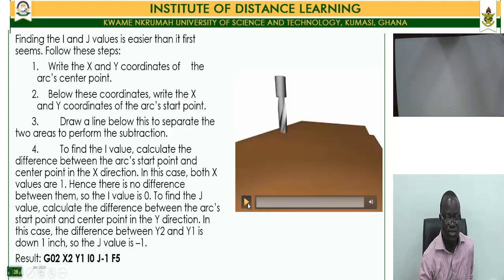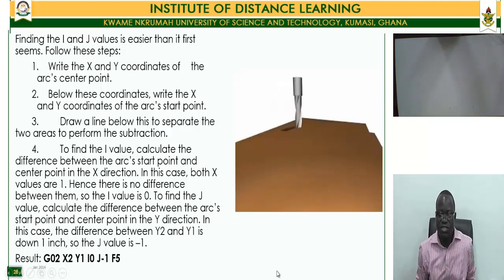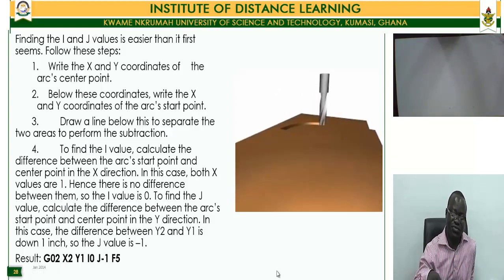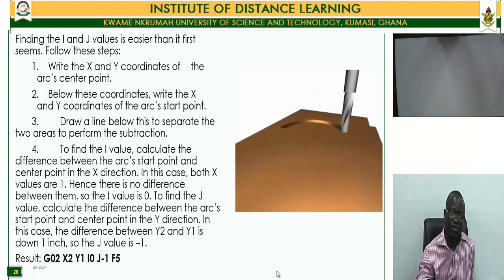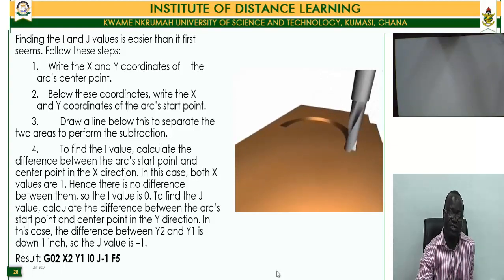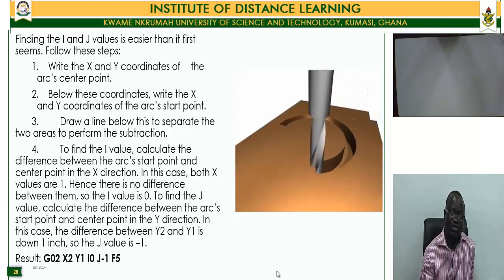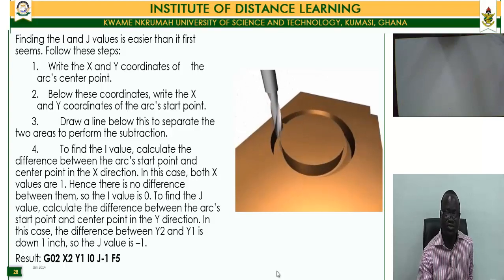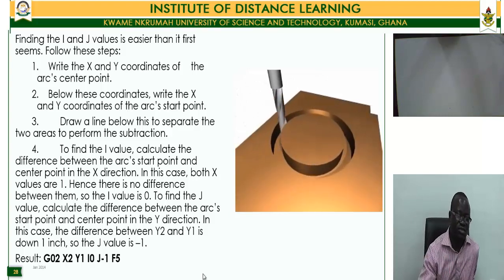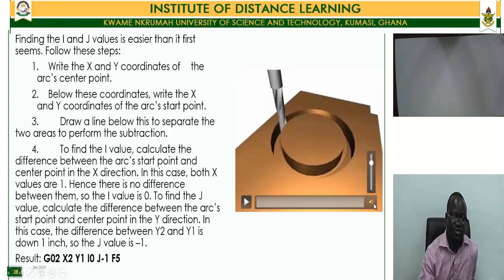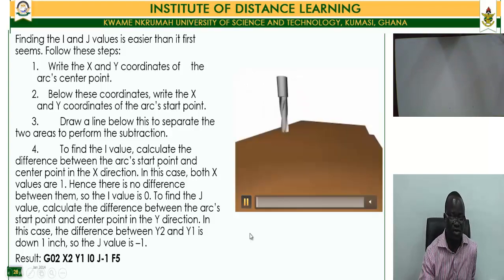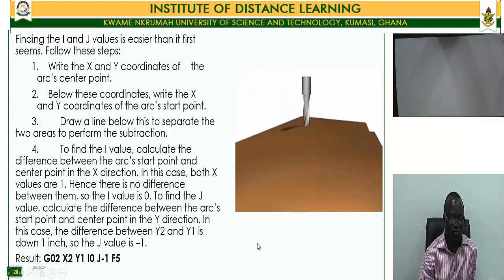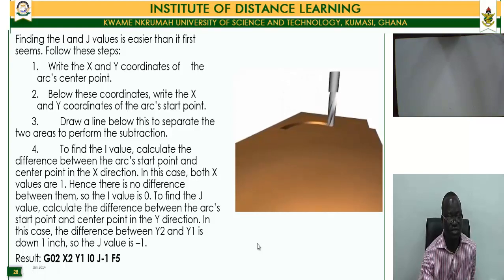So this is how the G02 command actually moves. If you look at it, it moves in this clockwise direction. Depending on the start point and the end point, if this circular interpolation in the clockwise direction comes back to the same point, it will generate a full circle interpolation. So depending on the final coordinates that you give, you will have a full circle interpolation.